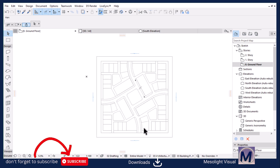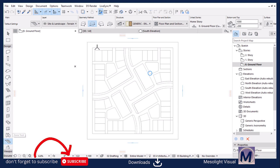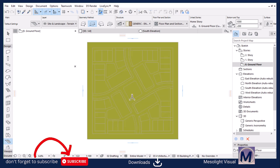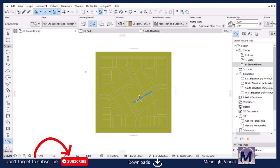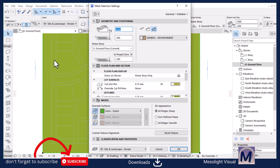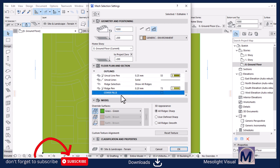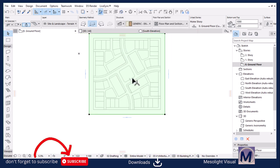So from here, like I said, we move forward to now modeling this site. The first thing to do is to use a mesh to draw, I'm just going to use a mesh like that to place just the whole site. And then let's select it and then open its settings. I'm going to get rid of this green stuff. It's because of the floor plan settings. And then I'm gonna switch off the cover fill, then hit OK.